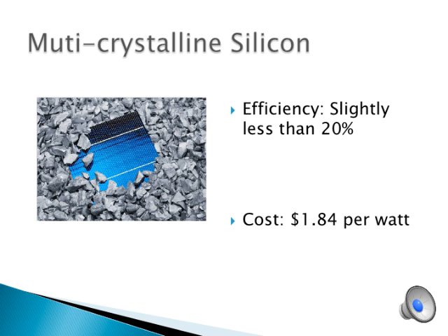Multicrystalline silicon is fabricated from blocks of molten silicon carefully cooled and solidified. Multicrystalline silicon is composed of several crystal structures separated by grain boundaries. The presence of grain boundaries results in lower material quality, which ultimately lowers the efficiency of energy conversion.